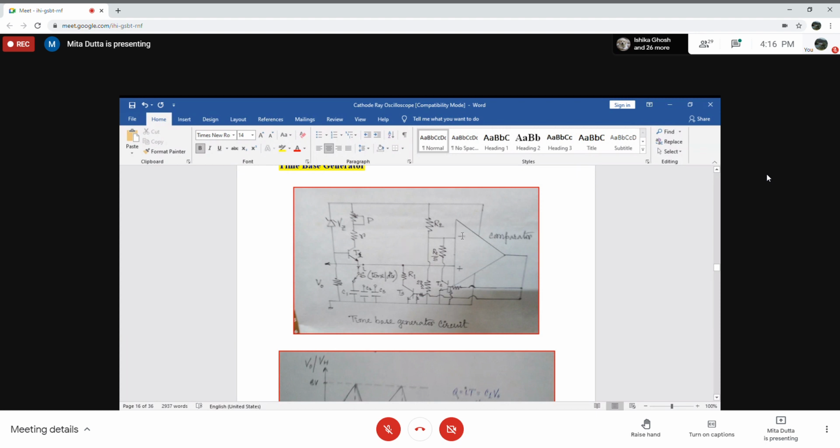Now, at this instant, the voltage across the negative input terminal of the comparator. What we have seen, the negative input terminal of the comparator is connected with resistance R2 and 2R2, and this is grounded. So the negative input terminal voltage is 2/3 VCC. Clear? Where VCC is the op-amp supply voltage, which is equivalent to plus minus 12 volt.